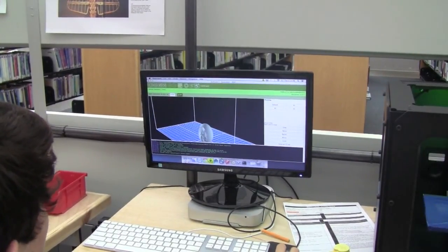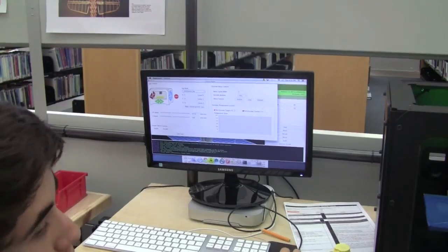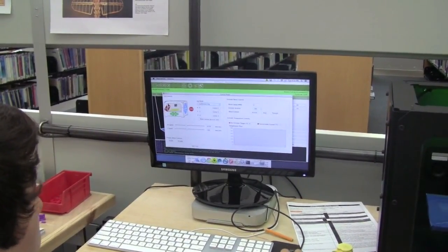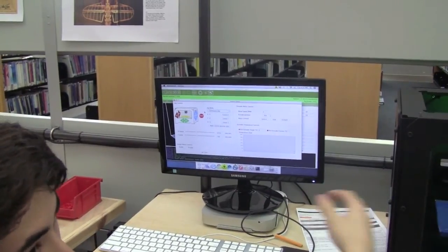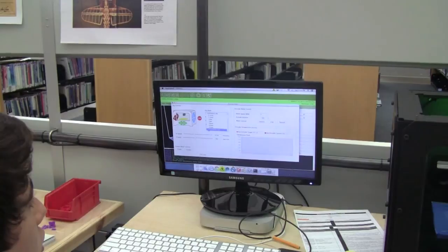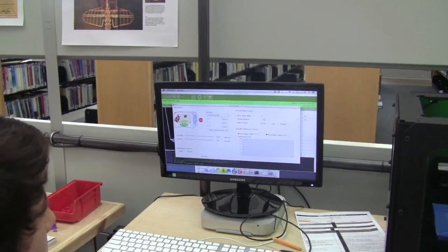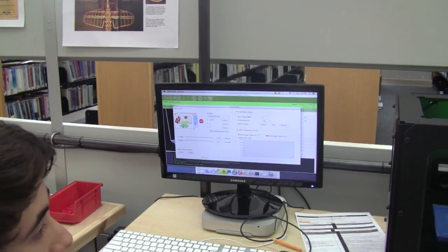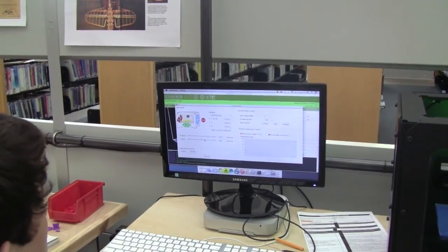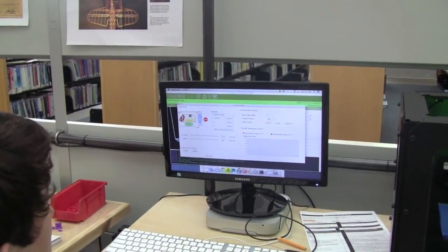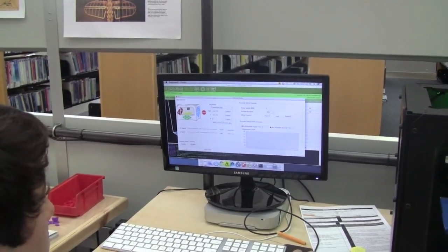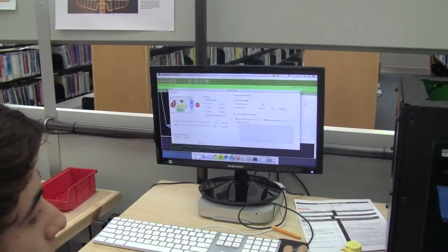Next, I guess I can talk about the control panel since this is software based. In the control panel, you can control the motor, so you can move the motor around and also move the platform around. If you have continuous job run, it means that if I hold down one of these buttons, your extruder will continue moving for as long as you hold the button down. So you can see here I can move my extruder left and right, forwards and backwards, and I can move my platform up and down as well.